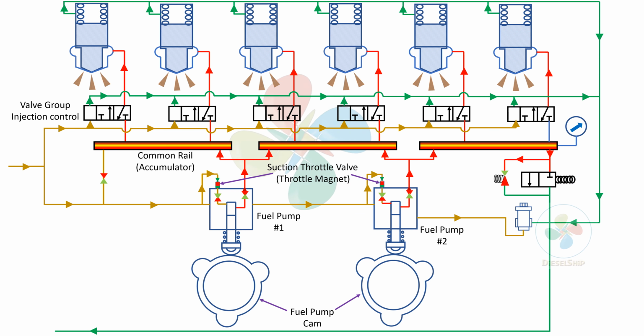And then the final thing is that this valve is an active valve. It is monitored by the injection control module, and it gives regular feedback of its condition. If the feedback is not received, or if the feedback is different from what it is supposed to be, the engine throws an error and does not start. Even the failure of one valve group will trigger an alarm and the engine will shut down, or if it is in stopped condition, it will not start.